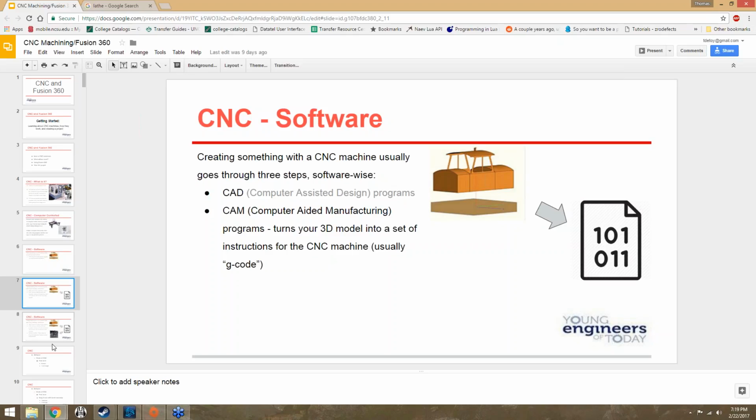And then they turn it into G-code, which I think I showed you guys, maybe? Anyway, G-code is simply sets of coordinates. It's really all it is. When these algorithms go through and determine the shapes, or they break everything up into layers and determine the path of the tool, whatever the case may be, the end result is that they output a set of coordinates.